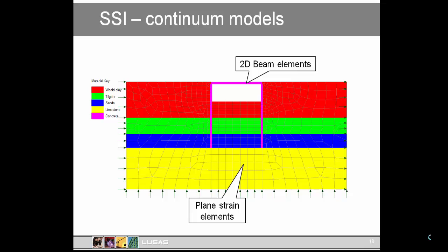If we add a vertical fixity and the soil gets sort of snagged up at the sides, and this actually changes the results in the area of interest at the structure, then the soil block isn't wide enough. So we need to make it wider and add more elements. It's important to have the flexibility to just be able to stretch the model out without redrawing all the elements. And for the bottom boundary, the horizontal boundary here, we just have to make the model deeper again until the change in key results in our structure is negligible compared to other assumptions inherent in the analysis.